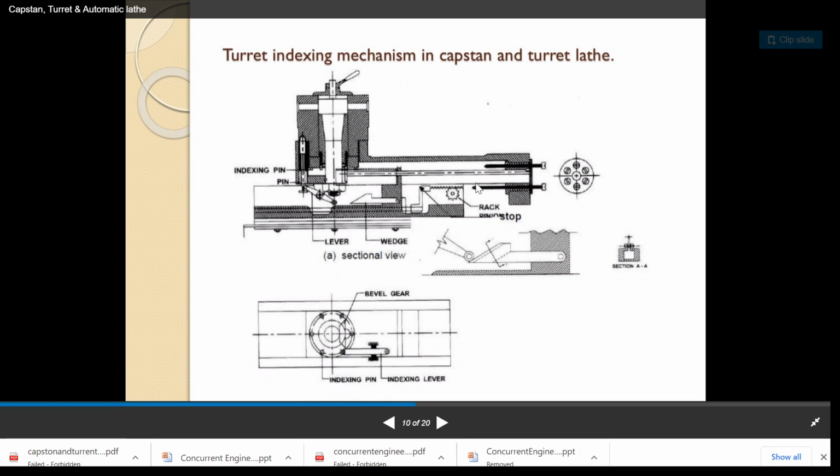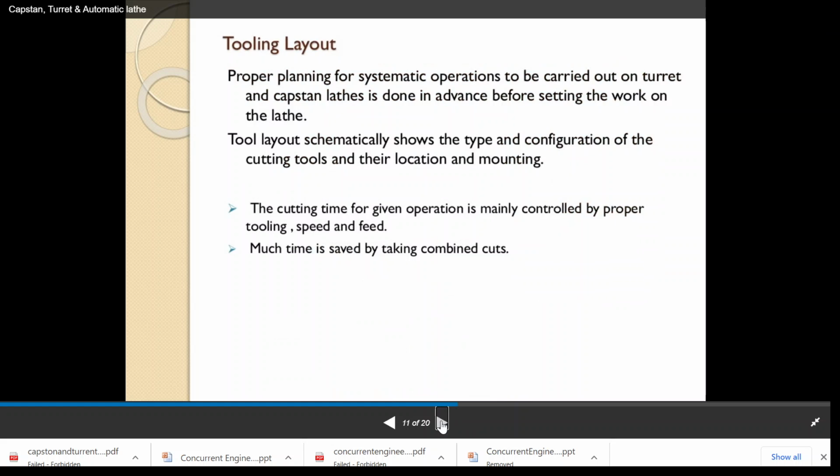And these are the stoppers. These will actually control the reciprocation, or the stroke length of the ram. This is actually the nut. We can rotate this bolt, and we can adjust the length. So these are the two important mechanisms incorporated in both the machine tools.